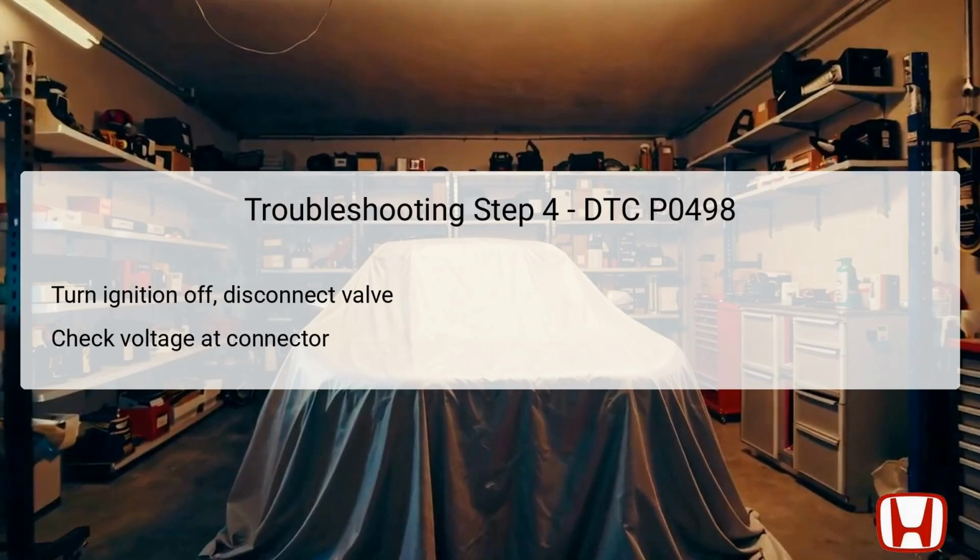This is crucial to determine if battery voltage is present at the connector, indicating that the electrical supply to the valve is functioning properly. Understanding voltage readings in this context is essential, as inadequate voltage can reveal faults within the wiring or components that require further investigation.